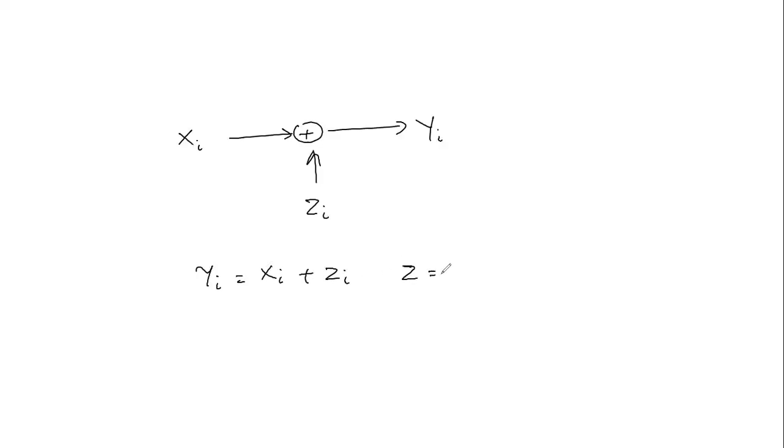Okay. So we already mentioned that we have the input, S sub I. It goes into the channel. Then we have the noise, Z sub I, and then we expect an output, Y sub I. And the model in this case is that Y sub I is the same as the input signal plus the noise contribution, for which Z has a normal distribution with zero mean and N variance, the noise variance.